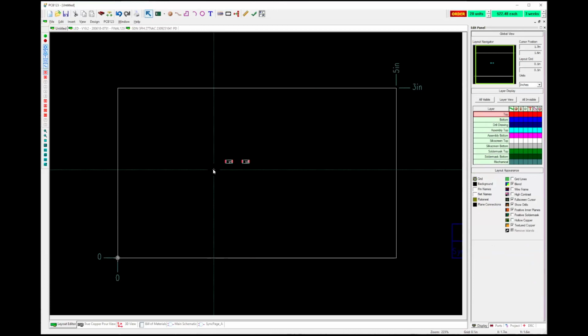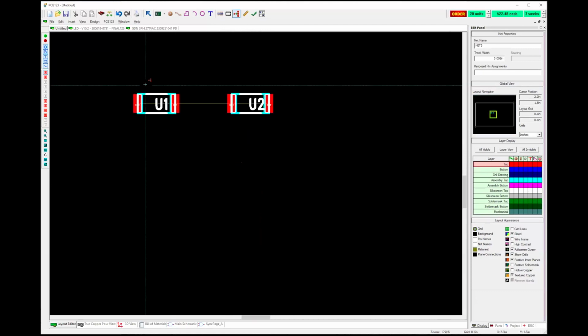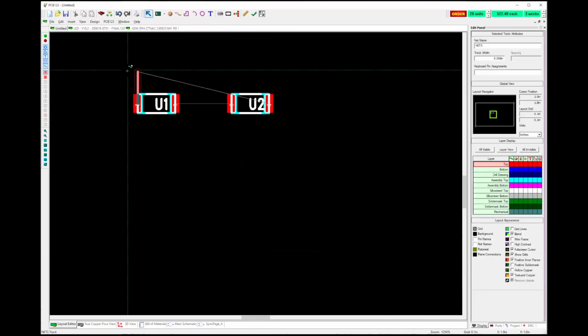So what that gives you is the ability to place parts quickly, without a specific part number you need to use. You just know that you want a resistor, and you'll tailor that as you go. I want to hook the wires up, so I tell it I want a connection from here to here. Escape. I want a connection from there to there. This is nothing you'd ever do because it's not really a circuit, but I'll be able to show you how to hook it up using the connections.